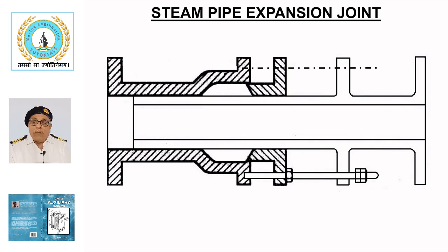Thermal expansion and contraction can cause pipe bending or buckling, leading to rupture and leakage. Similarly, flexing and twisting of the ship's hull due to wind and waves may cause misalignment, also resulting in pipe damage and leakage.